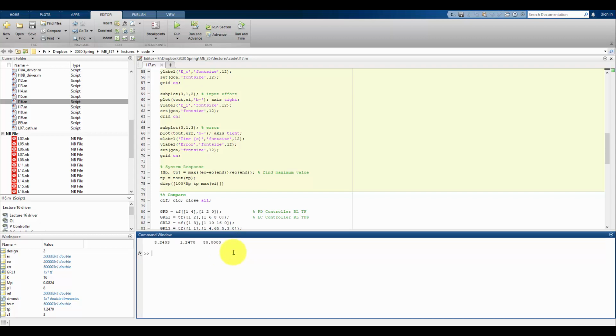So compared to design 1 and to the baseline, which actually were the same, here we have a higher max overshoot and we have a lower peak time. And that's being caused by the actual system having that extra pole and that extra zero. And in this controller, we have a higher maximum input of 80 than we had compared to the first design. So we'll compare all three designs at the end for a true comparison of all the choices we made. But so far this controller is probably not as good as the first controller because the performance doesn't match what our desire was in terms of the overshoot and the peak time. It also requires more of this input effort to get where we need to go.